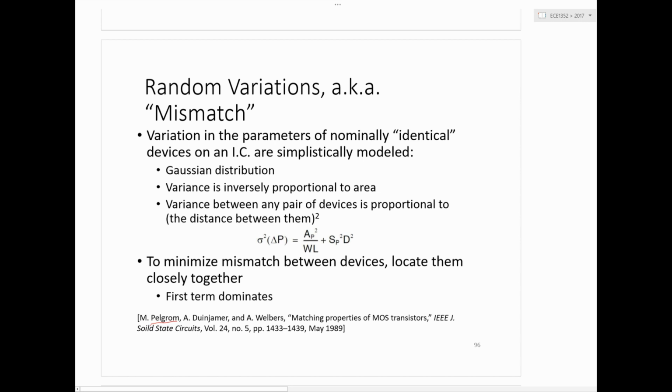And it basically says that if you have a parameter P of a component on an integrated circuit that you care about, could be the sheet resistance, could be Cox or mu or whatever, some parameter that you care about of some components, the statistical variation of that is going to vary with a Gaussian distribution at random, just because of random stuff that goes on. That was the model anyway, okay?